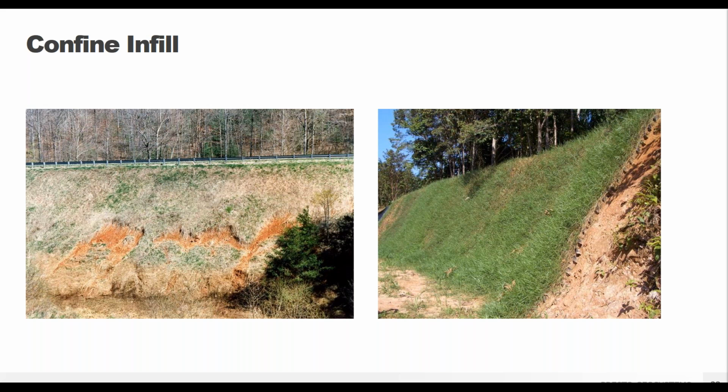And it is important to reiterate that the proper installation of the GEOWEB system includes that horizontal embedment of the GEOWEB into the crest of the slope. This prevents water from flowing beneath the GEOWEB system and undermining it. So you're not going to see rills or gullies forming underneath the panels that could potentially lead to failure.